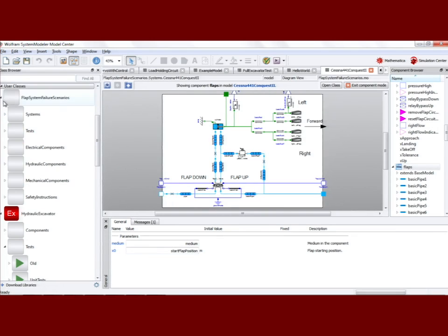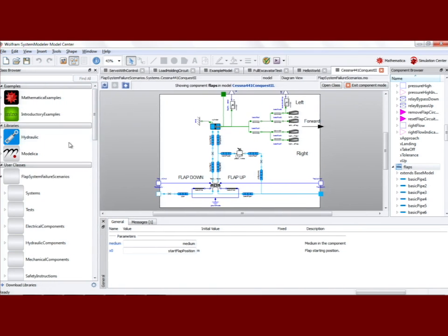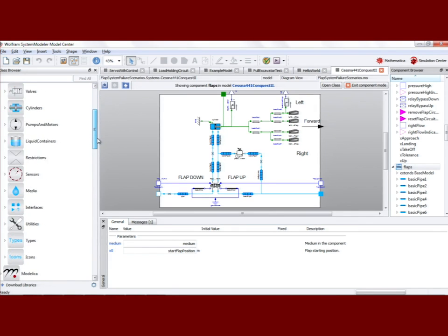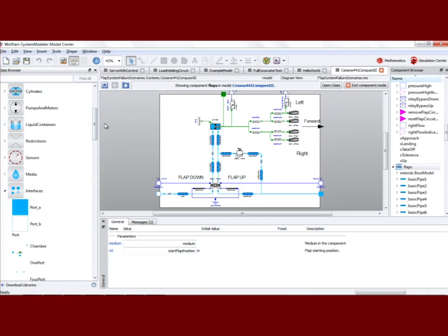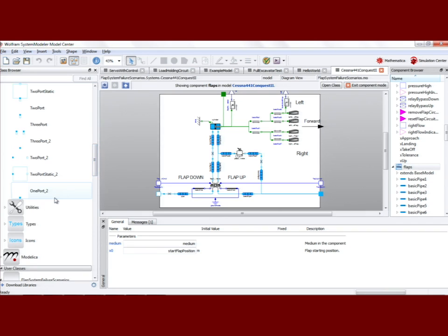If we look at the library, it has parts that are components that you build up the system from. The interfaces here, for instance, have the standard ports, the standard types like that. You have static models that are base models. You have models for leakage, for friction, and so on. And those you can use to drag and drop together your new system. Or you can add your own equations, do your own completely own version. So it depends on how close you are to what's available, if you will do it drag and drop, or if you add your own specific equation.